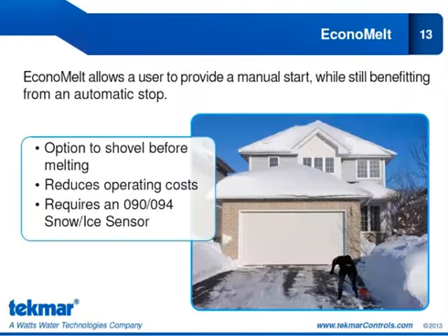Econo-melt is a new feature for the Snow Melt Control 654, and that will allow you to install a 090 or 094 snow ice sensor. But instead of having the automatic start, it will allow you to give it a manual start. And you still benefit from the automatic stop. Now, why would someone want to do that? Well, as the name implies, it is the economic way of doing snow melting.